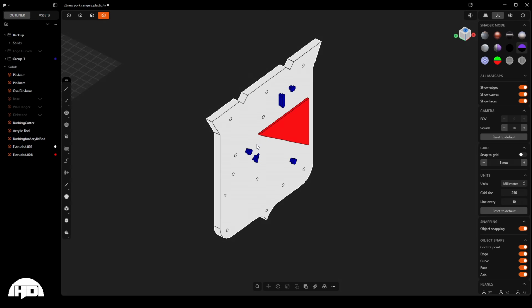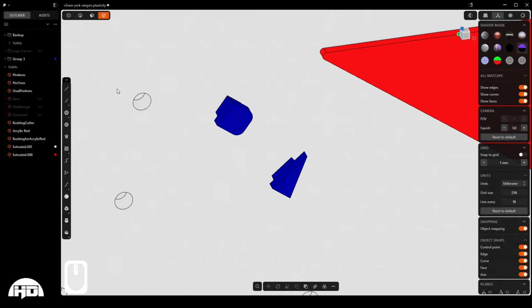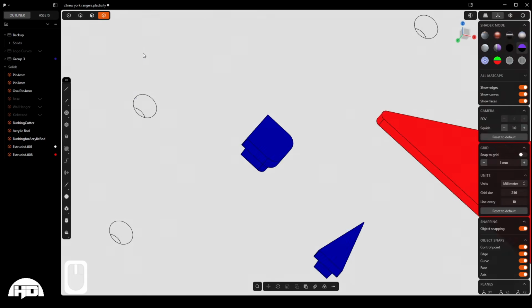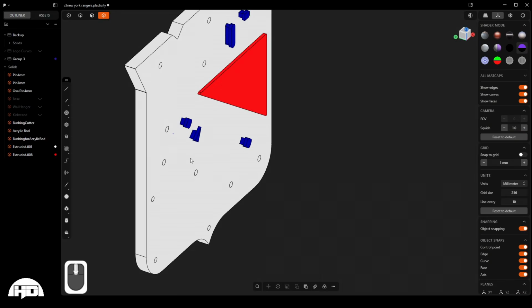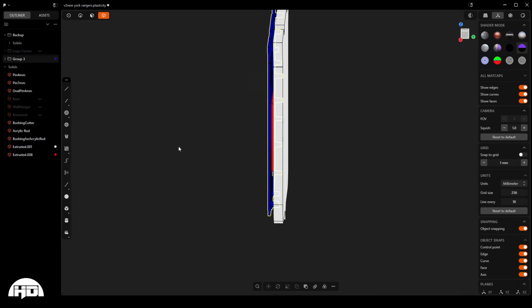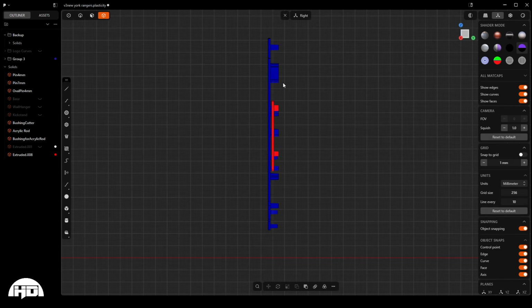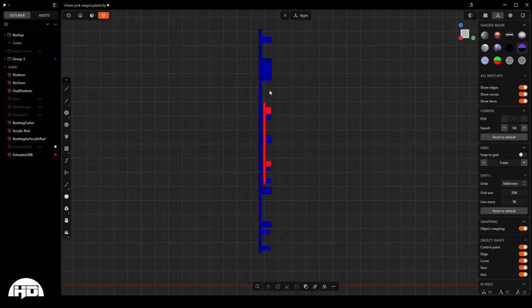But we're almost there. As you know, that made a completely perfect cut using the pins. Now, in real life, there's no completely perfect matching of anything, so we need to add a little bit of tolerance there for the 3D printer, for the final object to be able to snap in there. So let's do Control Z to unhide that. We're going to hide the base. H for hide. 3 will get us to perfect side view. And then we're going to select 3 for face.